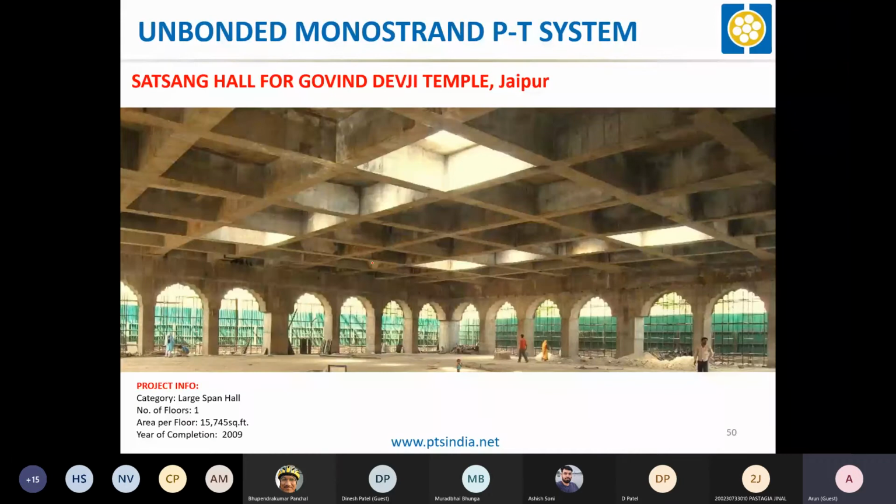Okay. So this is the building after construction. You can see that a grid or waffle kind of arrangement was there. Beams are in both directions, and the depth of the beam was around 54 inches, but it matched their height restrictions.